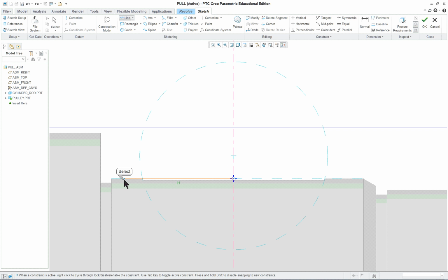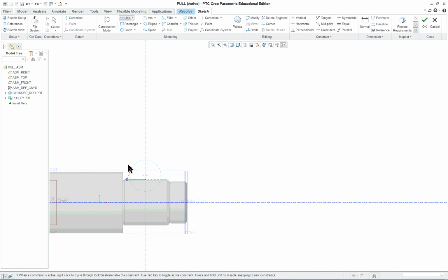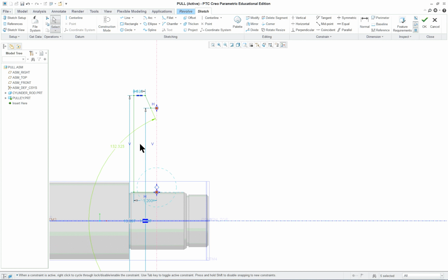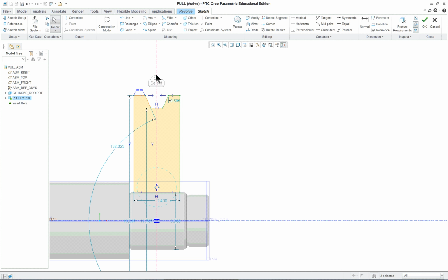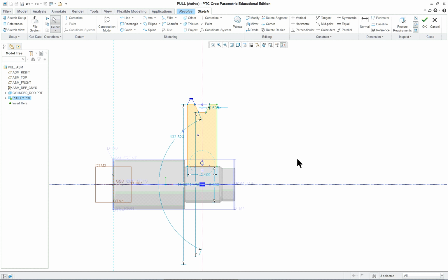And I'm going to come over to here. And I'm going to go up and over, a little bit of an angle. This represents the V, middle mouse button, a couple of times. So there's my geometry. Don't worry about it right now. Select all of it and go up to the mirror command and select your axes, or I should say center line, you put it there. And there's our cross section.